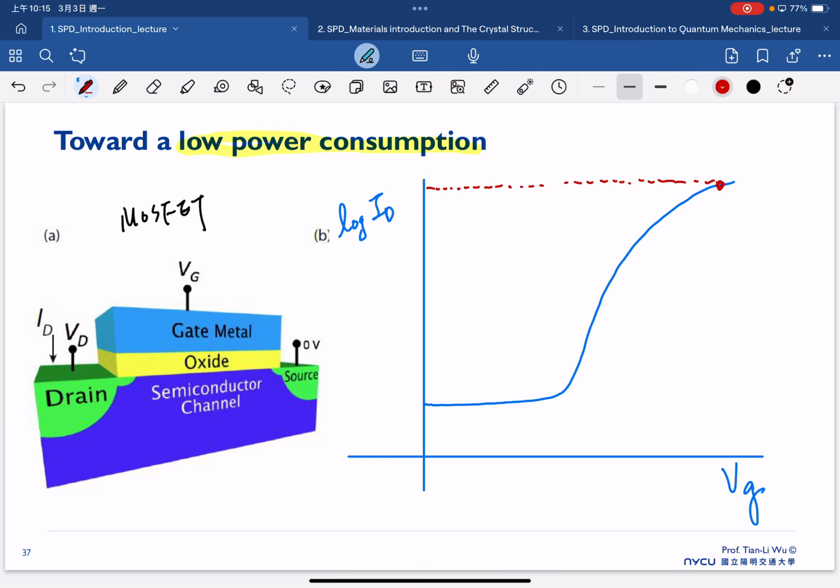So the spec for our product is that we hope this transistor can deliver such level of the current here. To deliver such level of current, this transistor needs to be biased at, for example, 1.5 volt. So that's typically why we have to make it a high performance transistor, because in the end we want this transistor to deliver the current that fits our product needs.